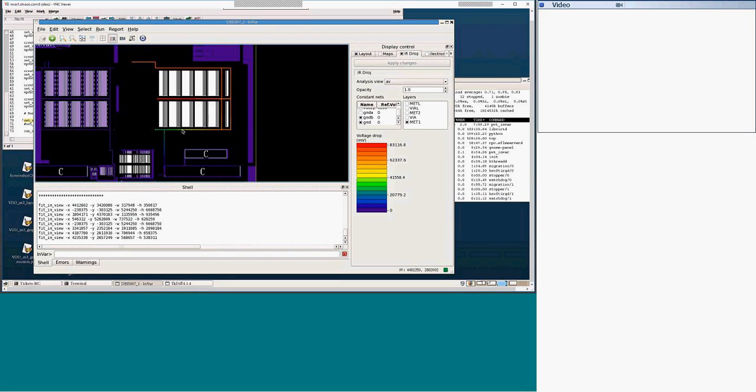I have a question. You mentioned layer. You can define an N well or P well. So for the IR analysis, there is a current path going through substrate or N well. Would we have the ability to see it, right? No, unfortunately, no. For thermal purposes, you can define parameters, but for IR drop, you cannot operate with the substrate layers.